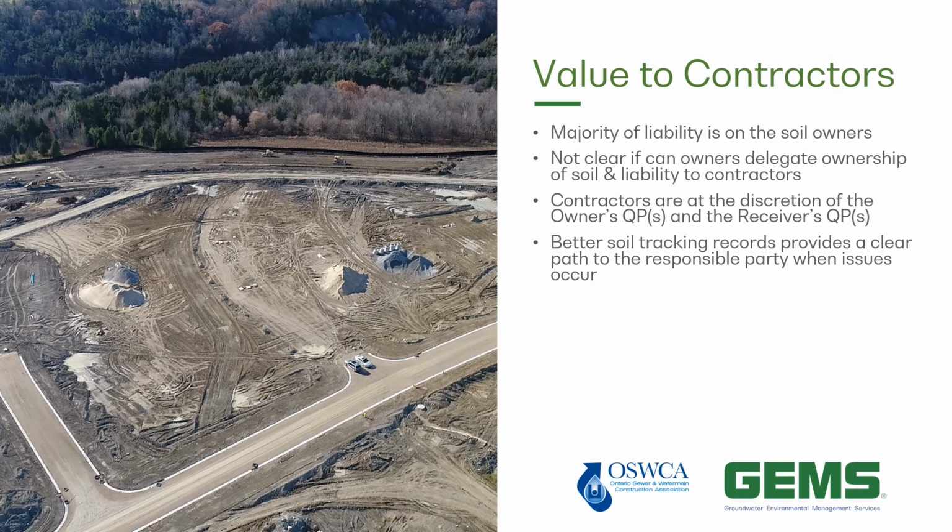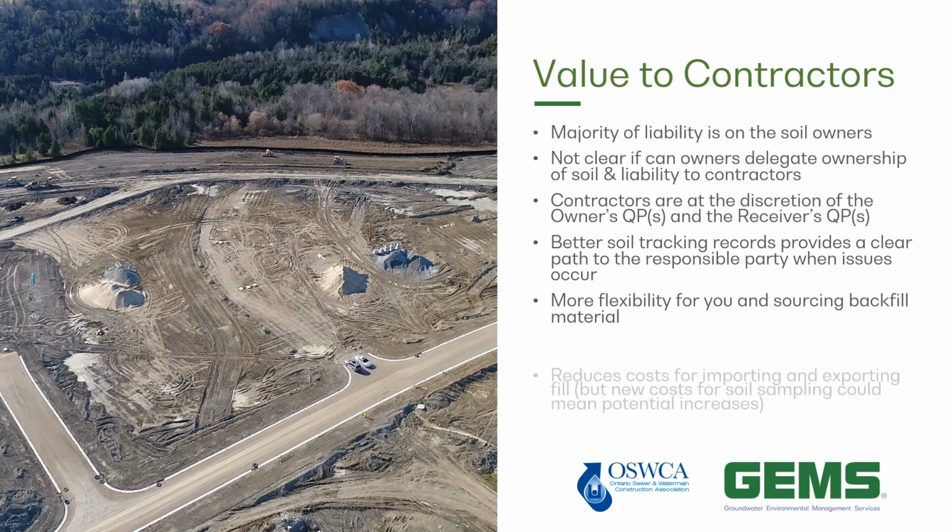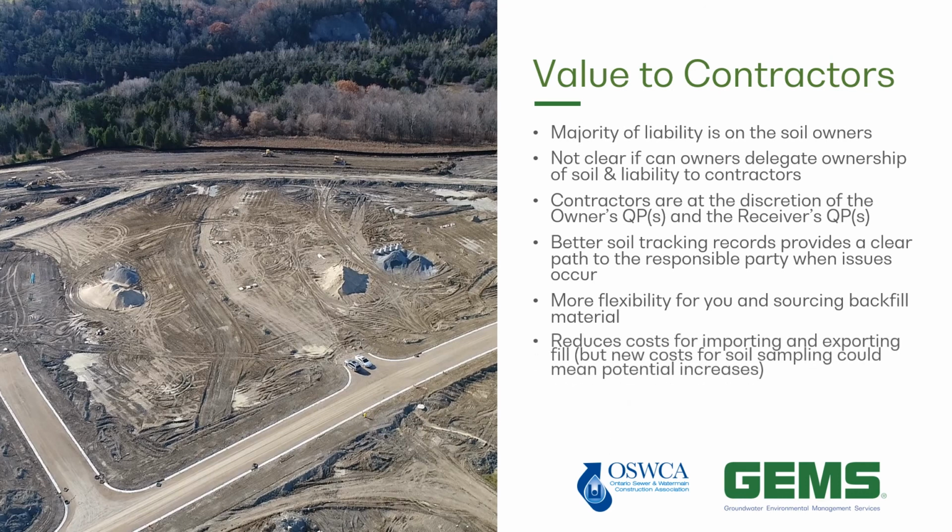There's also a lot more flexibility for you. Sourcing your backfill material may not be as big of a task as it has been in the past. If you have soil on site that can be reused and your tender documents and contracts allow you to use that as backfill material, then you don't need to bring any in. So you're talking about a reduction in costs for any importing of soil. Anything you're reusing on site doesn't need to be exported. So you're saving tipping fee costs if you don't need to send it to a waste site and you can reuse it.